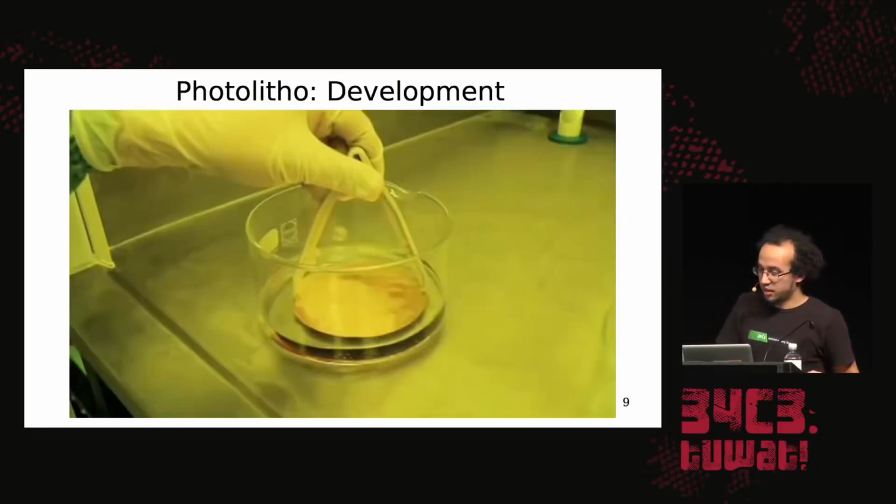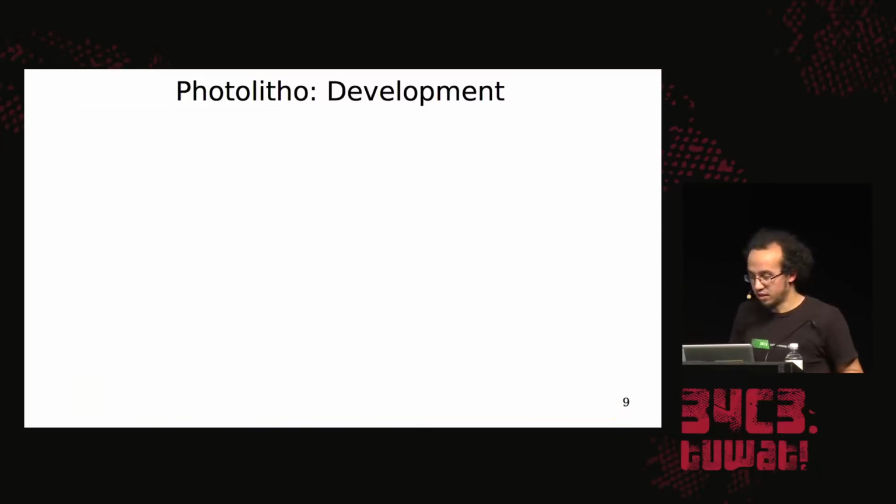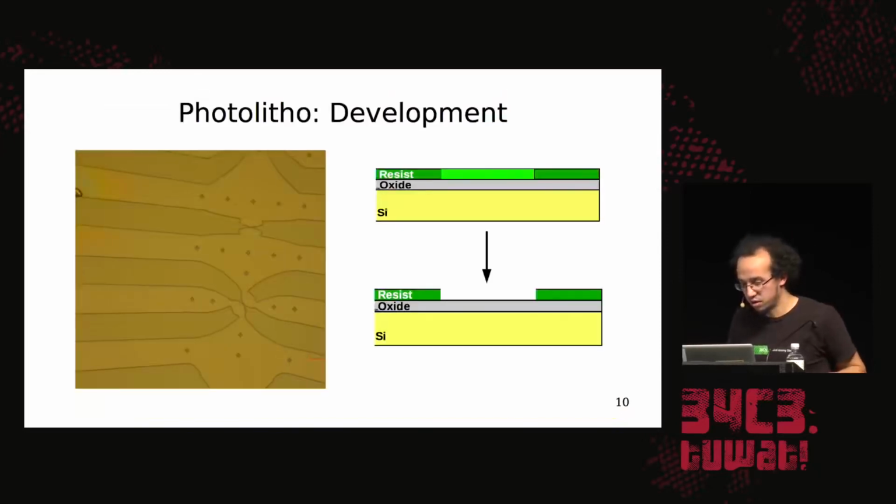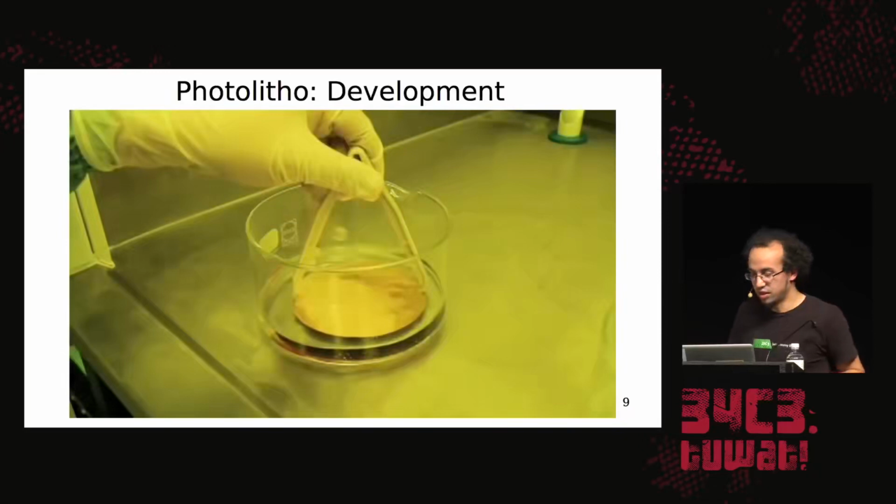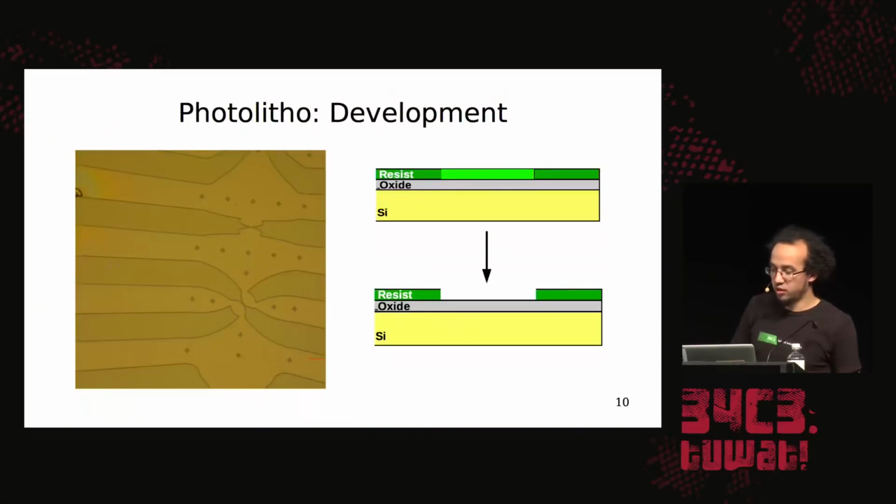So let's actually develop the resist, and that's now easy. You just put it inside. Okay, next thing that doesn't work. Sorry about that. So you just put it inside the developer solution, and this will dissolve away the exposed parts of the resist, and it might leave you with this thing here.